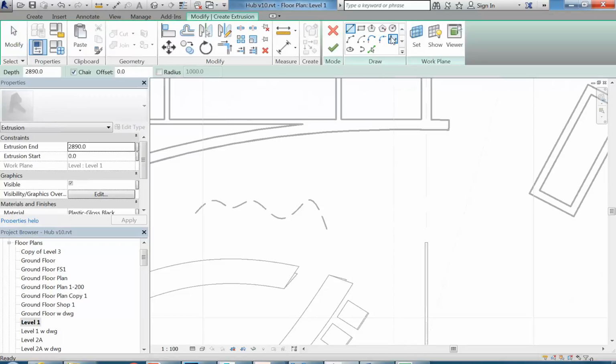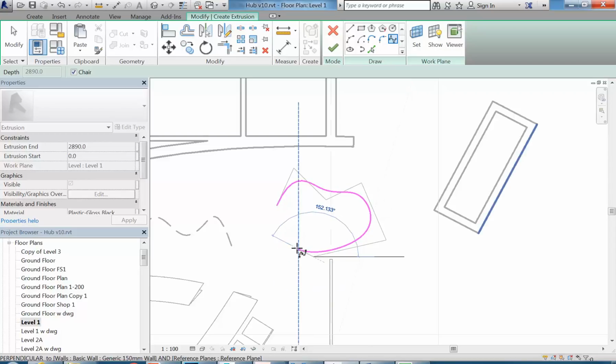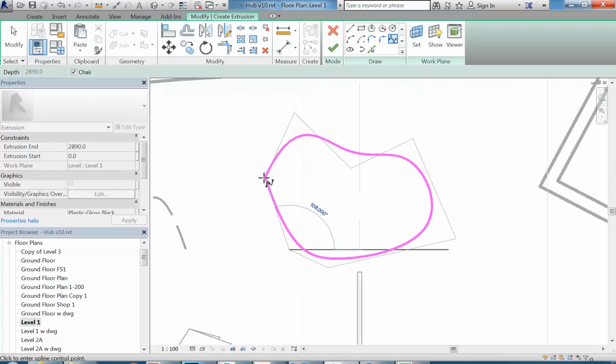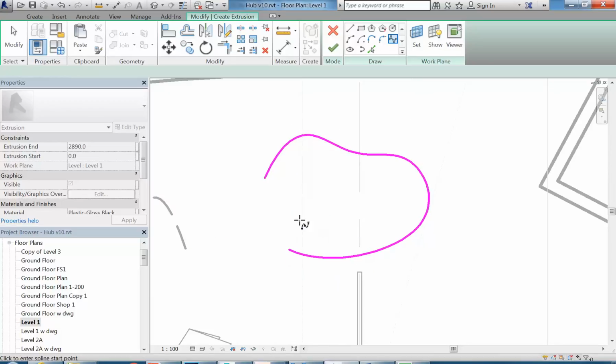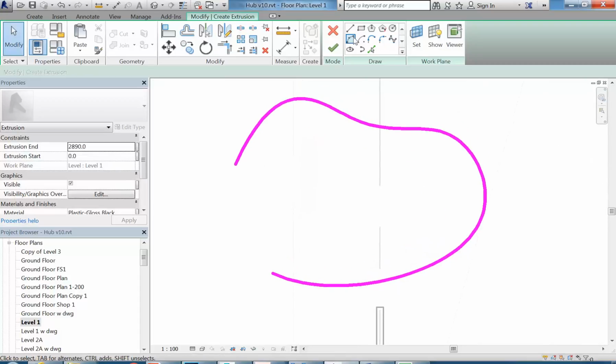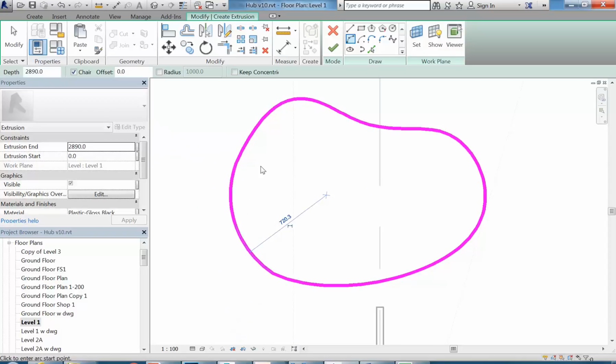Extrusion, so you've got the spline tool there, it works, but how do you close it? You've got to have a closed shape to make an extrusion. You can see it's not snapping to that endpoint. So what do you do? The answer is draw another shape. Usually I just draw an arc or something to connect those points, and that will close it.